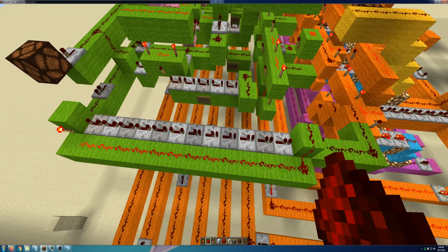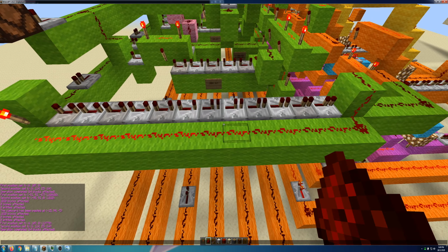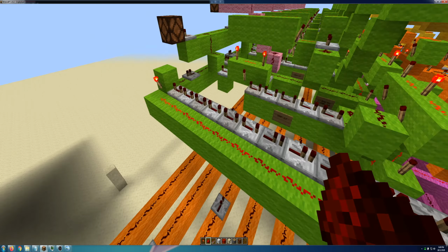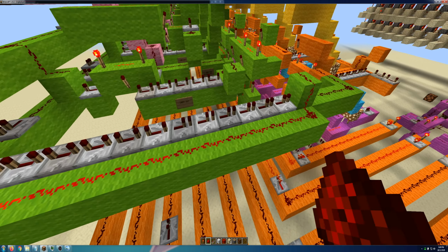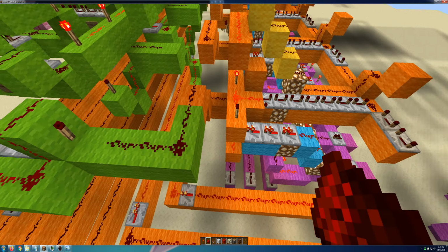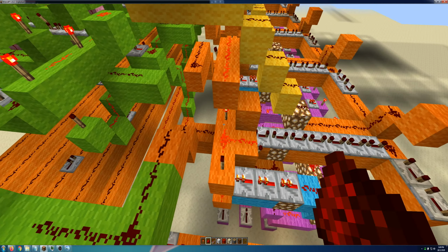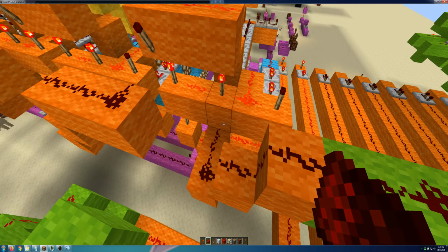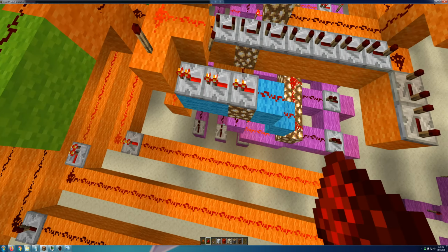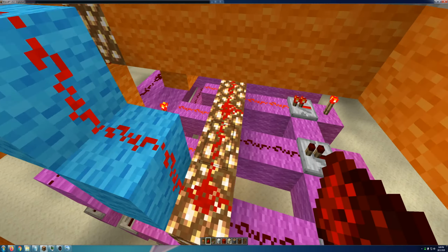Once the latch turns on, it will simulate a pixel draw function, and this does an entire row. So this is a gigantic pulse limiter, which basically gives a pulse of a fixed length, and then this goes into essentially the same thing. So we have here whether or not the pixel should turn on. That's determined by literally an OR gate.